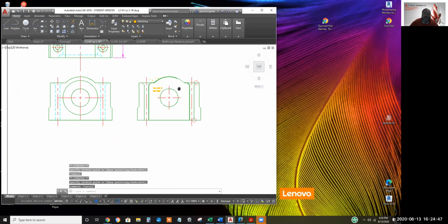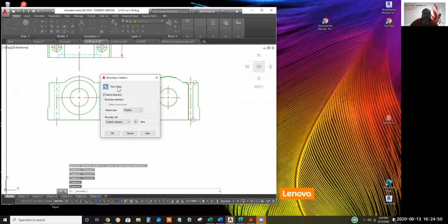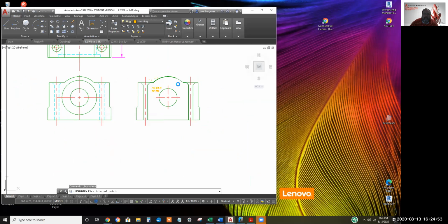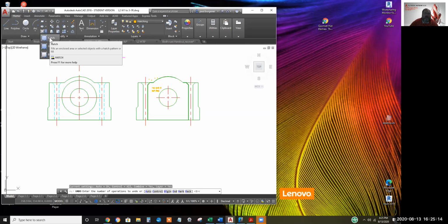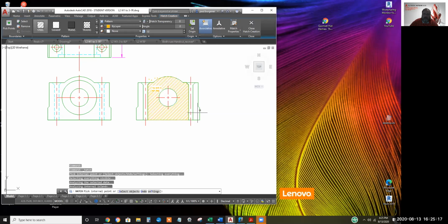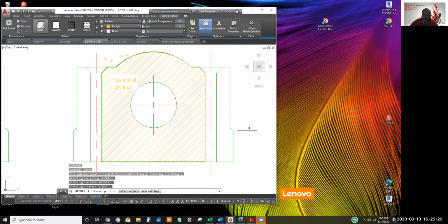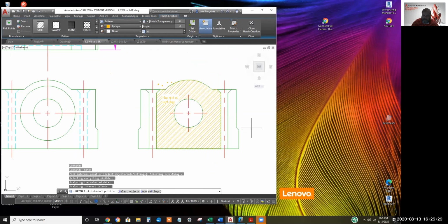I'm cheating a bit here for sake of speed. Okay, somehow I was on the boundary crosshatch. Let me start over again. Regular hatching. Click. Looks like the settings I had from the last cross-hatching stick. I'll hit enter to say, yep, that's what I want.